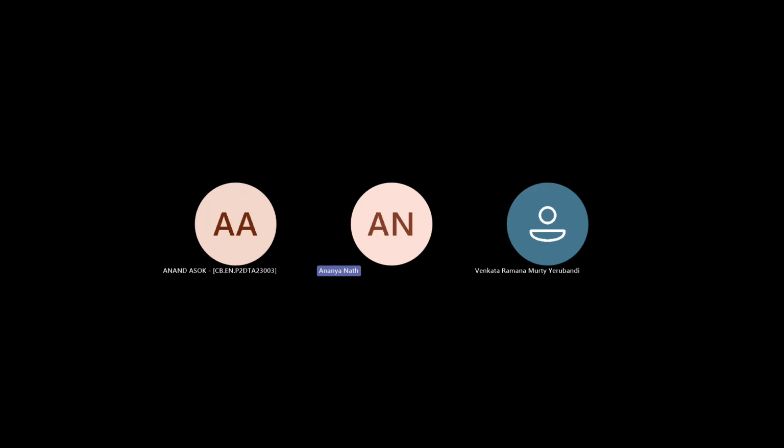Like I use SolidWorks, but SolidWorks is not good for doing this repair in reverse engineered CAD models, because after reverse engineering you get the STL, and correcting the parts in the STL is quite difficult. It's better if you can convert it to a SolidWorks or CATIA file and then rectify it there, then convert it into STL. There is no other way actually. You have to put manual labor into that.